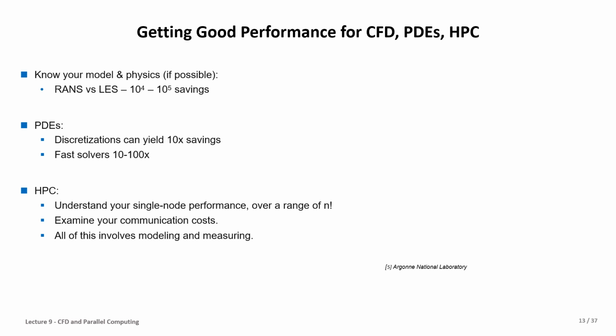Regarding the HPC, it's required to know the number of nodes and processors to make the performance of the high performance computing efficient. This also includes the model used, for example DNS, RANS, or LES, and also the architecture of the HPC system that you're using, to know the minimum number required to provide sufficient efficiency based on the points per processor.